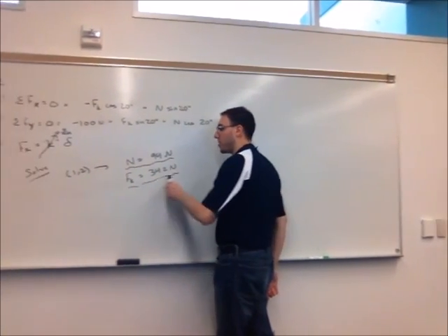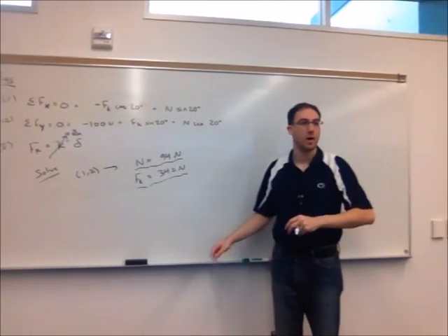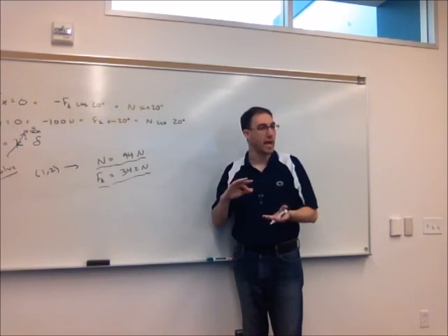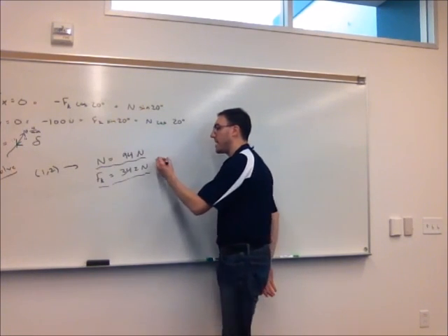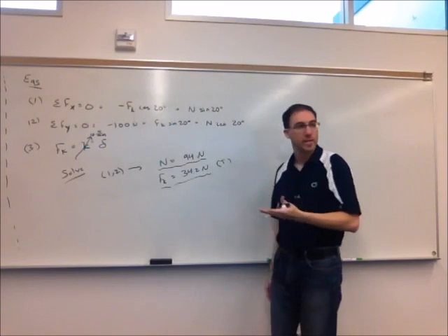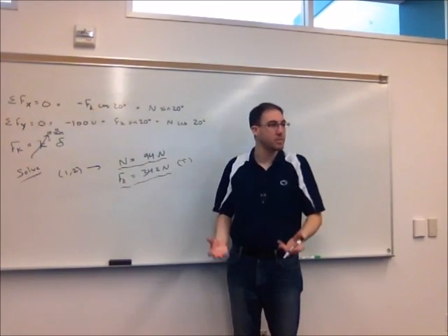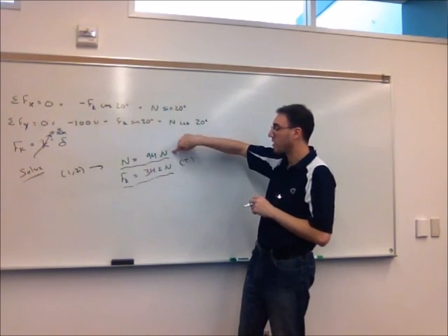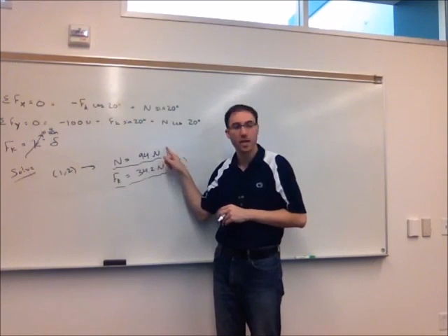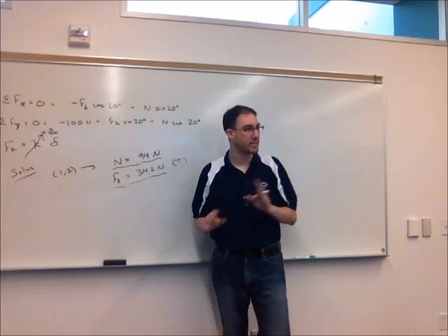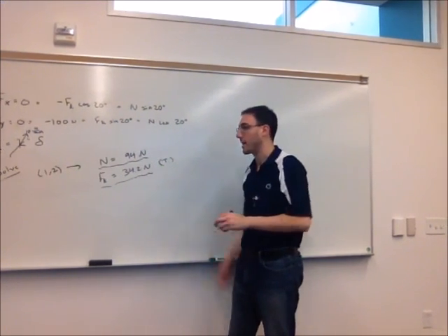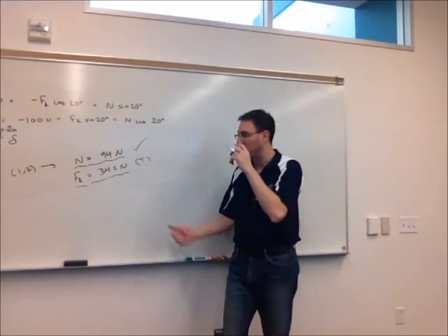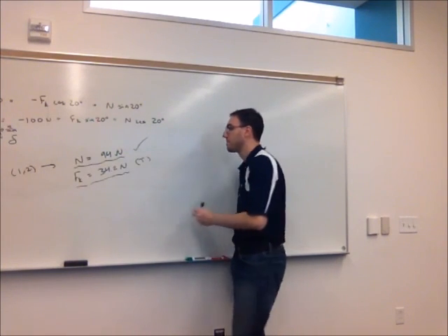So using equations 1 and 2, we find this, and it also could be a good check along the way. In this case, it's not a big deal because the spring force could be positive or negative. This tells us that the spring is in tension, which springs could be in tension or compression. We made the assumption of tension, but it didn't have to be. One thing, finding that normal force is a good idea here. Again, it's kind of a check. The normal force must be positive, or we did something wrong, either in the math or in the modeling. It is positive here, so that's kind of an intermediary check we can use. So positive normal force, that's a good sign.